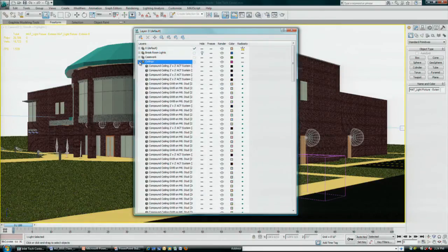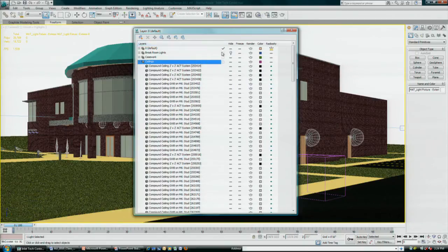Now, another thing you want to know about preserving the BIM is because we use this FBX mechanism, not only do we get the exact naming convention on all of our different categories and the components inside those categories, we also get the element IDs. So anything that changes in that model can be cross-referenced directly to an element ID.